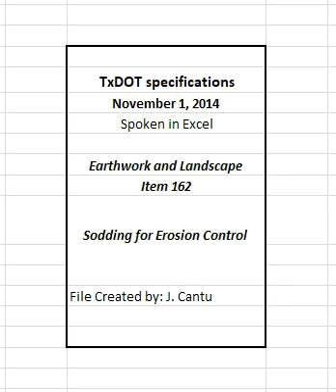3.1.2 Block sodding. Place sod over the prepared area. Roll or tamp the sod area to form a thoroughly compacted, solid mat filling all voids in the sod area with additional sod. Trim and remove all visible netting and backing materials. Keep sod along edges of curbs, driveways, walkways, etc., trimmed until acceptance.